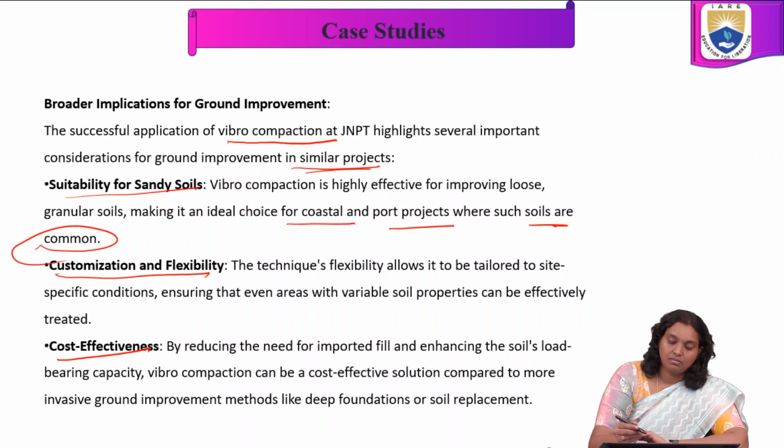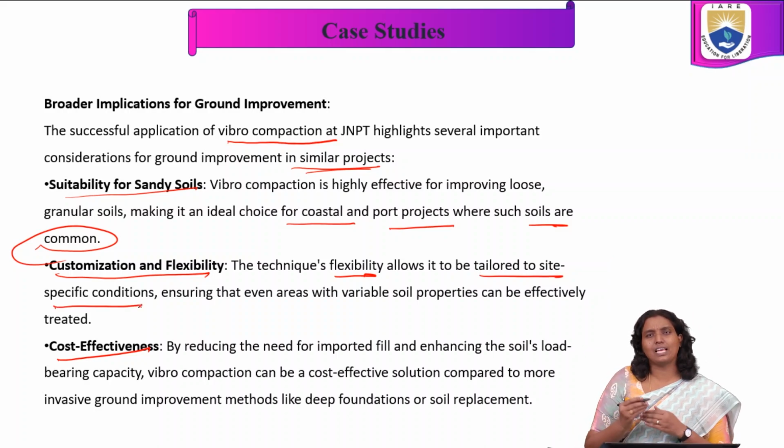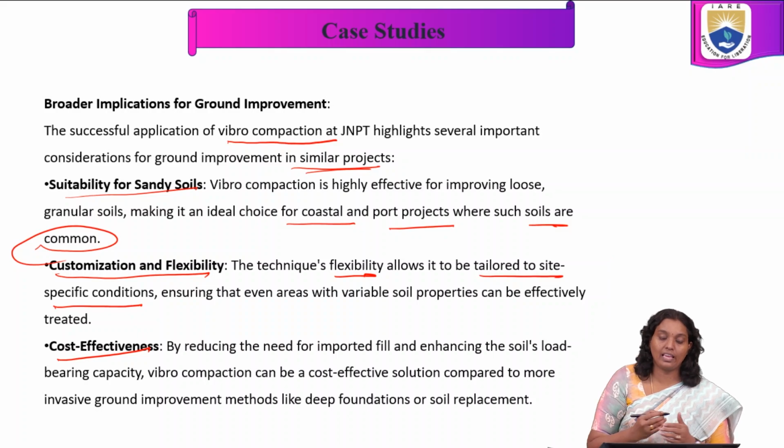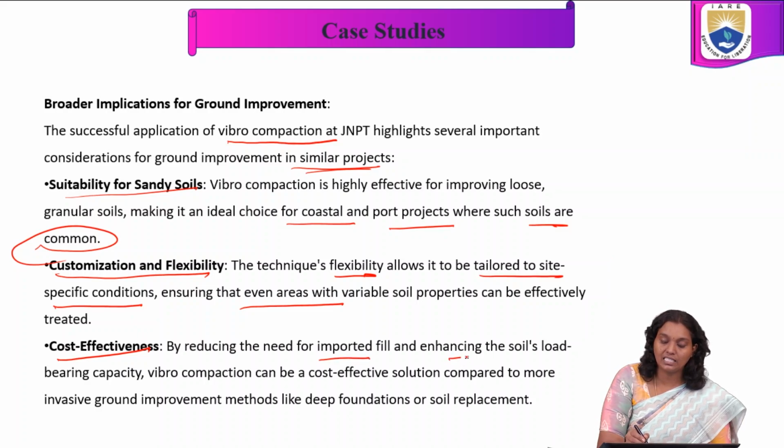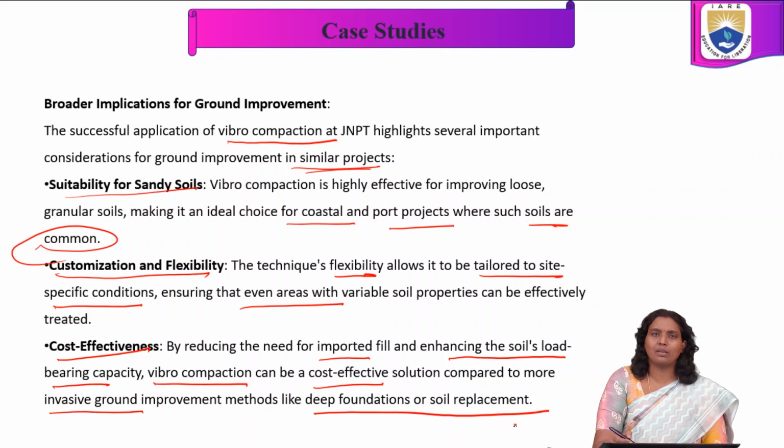The technique's flexibility allows it to be tailored to site-specific conditions, ensuring that even areas with variable soil particles can be effectively treated. In cost effectiveness, by reducing the need for imported fill and enhancing the soil's load bearing capacity, vibro compaction can be a cost effective solution compared to more invasive ground improvement methods like deep foundation or soil replacement.